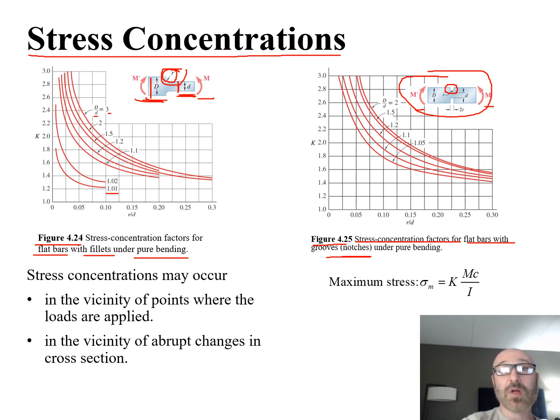And we can also say I've got my moments on this as well, which we can keep as a constant. The last thing that we do is little r over little d. For whatever problem we state, we're really just concerned with the geometry: that fillet radius over the width of the gauge length section. So that's our r over d, down here on our x-axis.